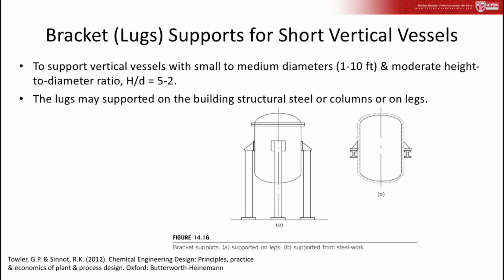So basically in the food industry, if the size of the vessel is not too big, the best thing is to consider legs, leg support, or bracket support or lugs. You need to consider lugs or bracket supports.